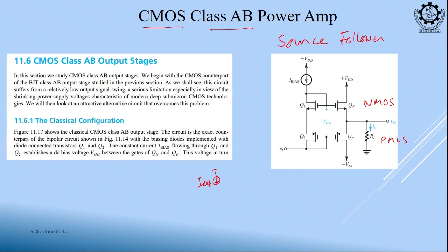So, for this circuit we need a current mirror. What is the concept? You use that current to generate a VGS. If I force this current to the drain terminal and tie this drain terminal with the gate terminal, this current will generate a constant VGS, just like if we provide a constant VGS we will get a constant current.